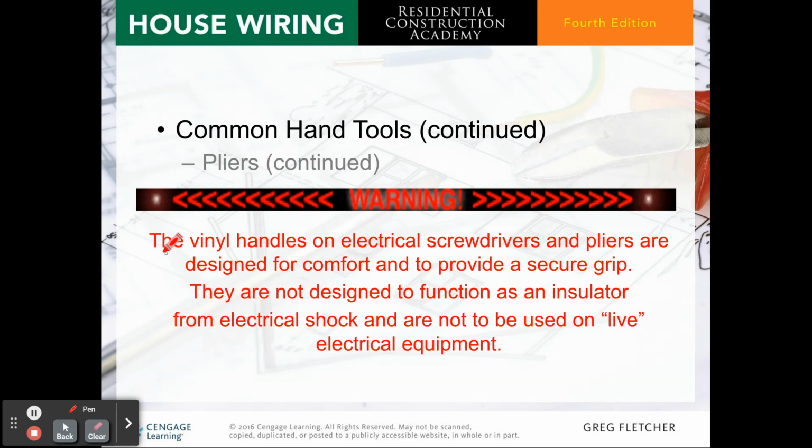As a quick reminder, the vinyl handles on electrical screwdrivers and pliers are designed for comfort and to provide a secure grip. They are not designed to function as an insulator from electrical shock and are not meant to be used on live electrical equipment. Again, they're only for comfort and to provide a secure grip.